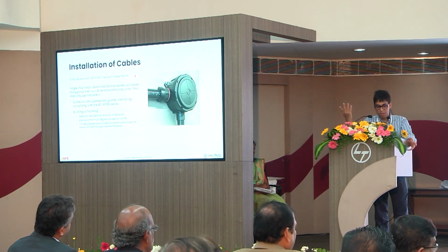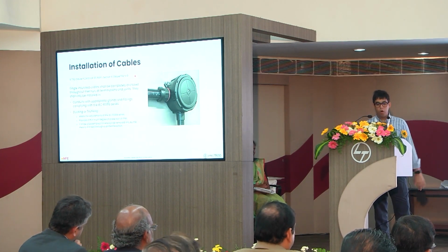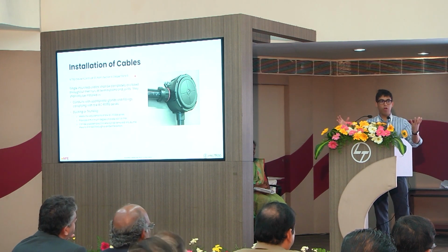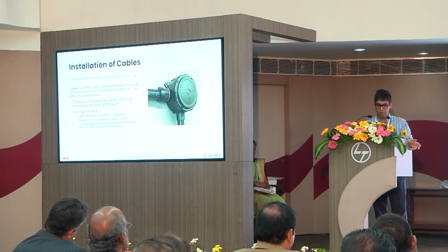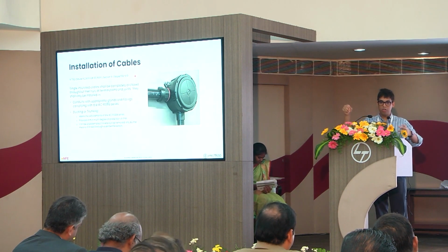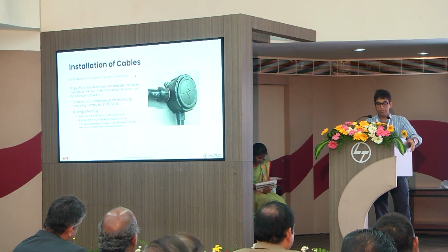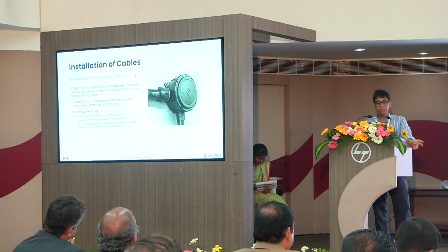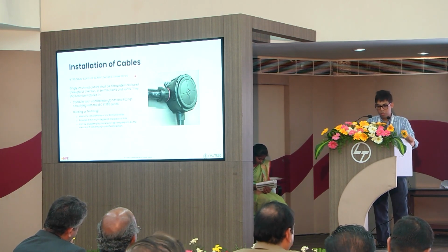And obviously it has to be earthed, which is a different story. And if it's not earthed, there are other considerations. Also, the cover should not be just able to come off. Oftentimes I've seen you go into a doctor's waiting office and they're very poorly installed electrical work. A child or somebody will just go and sit there and start fidgeting with the trunking or the ducting, and the entire casing, the top, will just come off. And then immediately you have, sometimes they put connections also inside, like they twist cables and all, which is a terrible thing. So this should only be removed by means of a tool or a very deliberate action. Like in the case of trunking, you snap it upwards and pull it out.